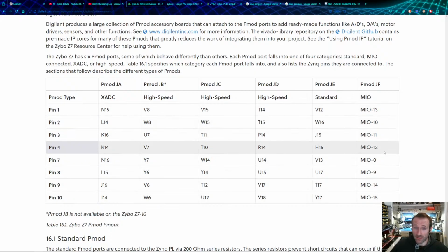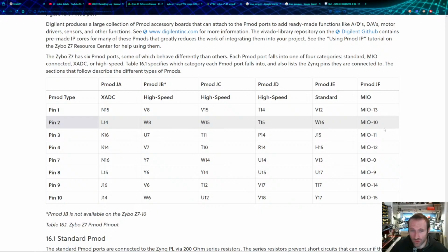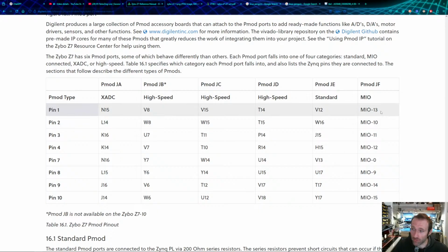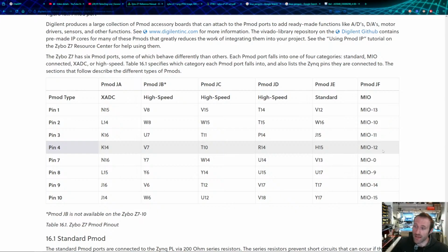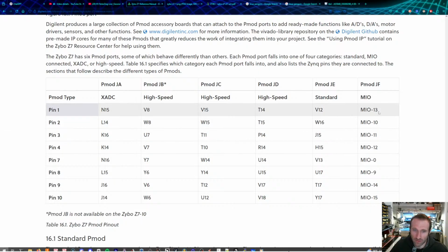This is free, this doesn't have to be SPI. There are other controllers that you can multiplex out of those IO ports. That's why this doesn't say specifically, oh, this is MOSI, MISO. These can be whatever you've mapped them to inside of the FPGA. This is one of the amazing things about working with an FPGA, is you have the ability to customize whatever you're outputting on the pin.